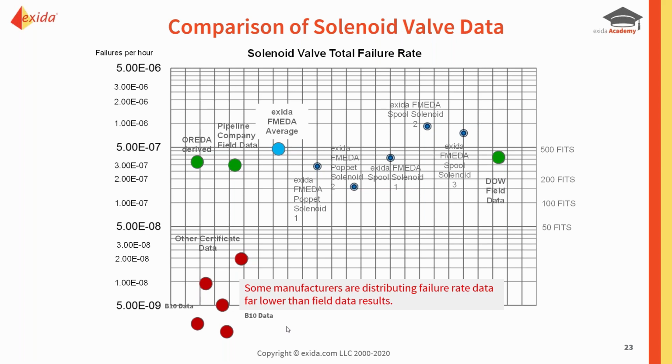So if you've got a dynamic device or dynamic application and you're worrying about wear out, the B10 is the way to go, because what it says is you have to take at least 20 devices or more, you cycle them at a given rate per hour, and then you record until 10% of the population fail. And at that 10% point, you calculate a failure rate.